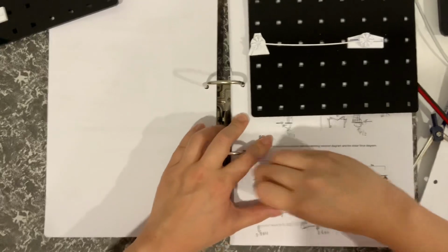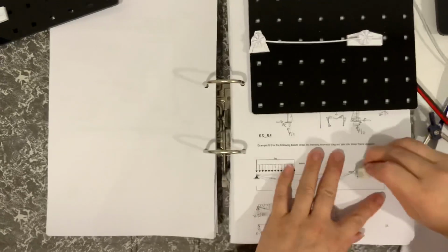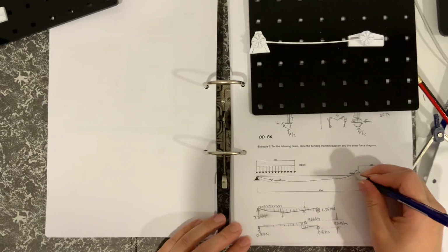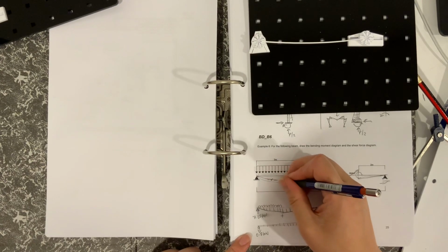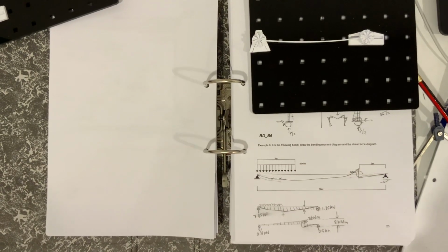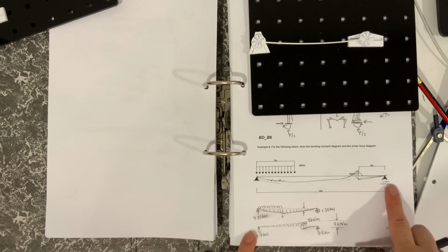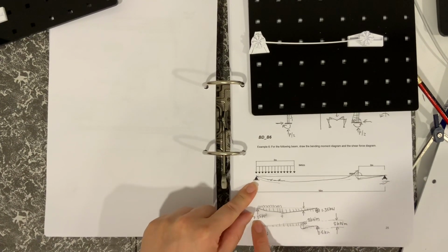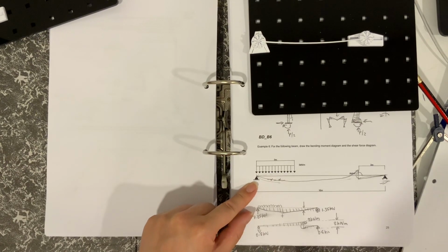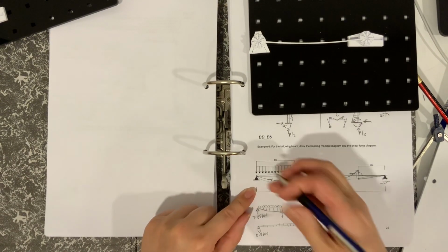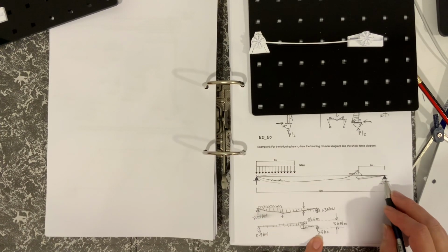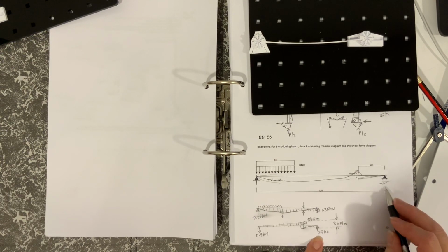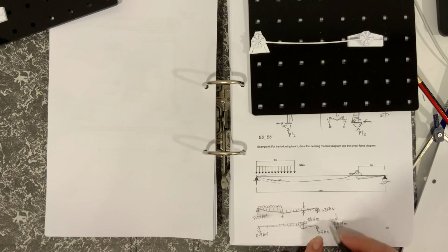So the point is you would be using the theorem of superposition to enable you to basically add the two bending moment diagrams together, and then that will give you the final bending moment diagram. And then you can use exactly the same technique for the reactions. So the reaction here would be 7.65 minus 0.8 upwards. And then the reaction here, I think both are acting in the upward direction, so it would be 1.35 plus 0.8 kilonewtons.